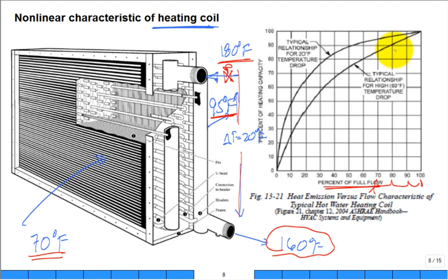You would think, or you would like, the total Q removed from the hot fluid and put into the air would go down proportionally. So that if you reduced it by 90%, Q would be reduced by 90%. But au contraire, no, no, no. If you have a 20-degree delta T for your design of your system, let's say you reduce it by 10%, what is the reduction in the Q?